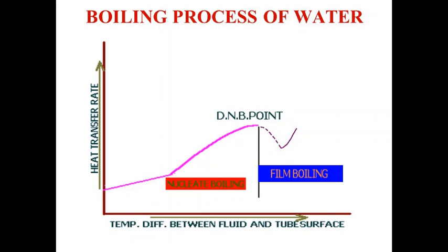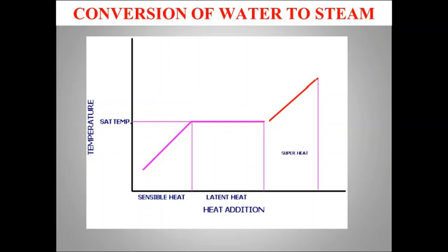As a result the actual heat transfer reduces, but the tube metal temperature difference may remain high with the bulk of the fluid, and after the entire fluid is again transformed into the vapor phase, we again find an increase in temperature with the associated increase in heat transfer rate.